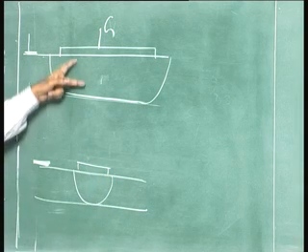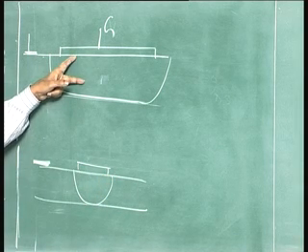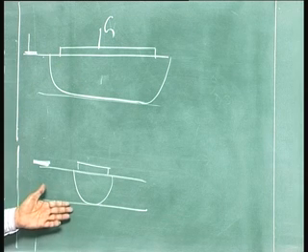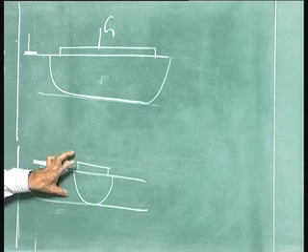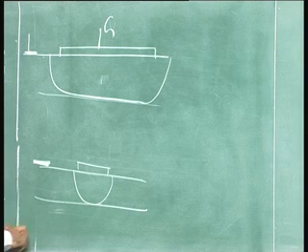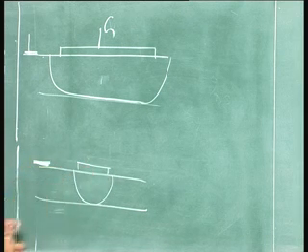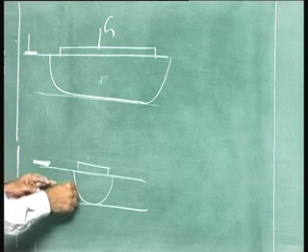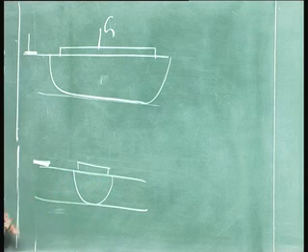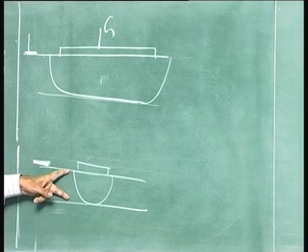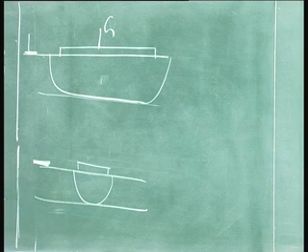This threshold will be larger than what we have seen. How do we avoid that problem? Make the thickness smaller, so that the depletion layer width is small compared to that. So, this curvature, you have a plane parallel portion there. So, you reduce the channel thickness, and it must be accompanied by the increase in doping.